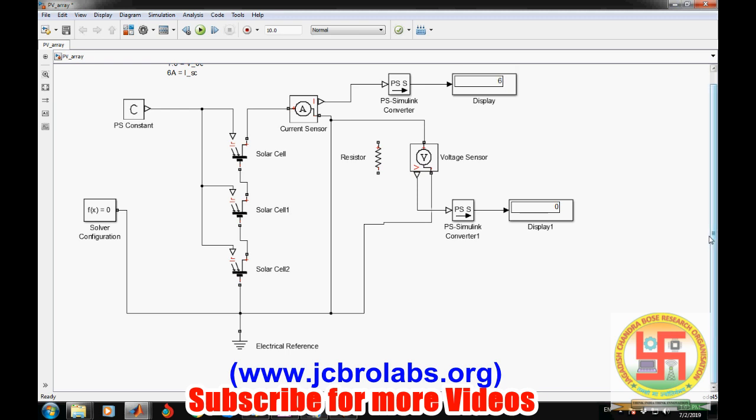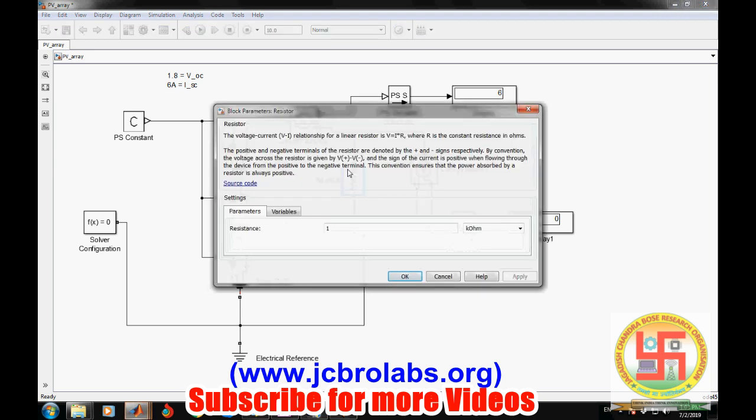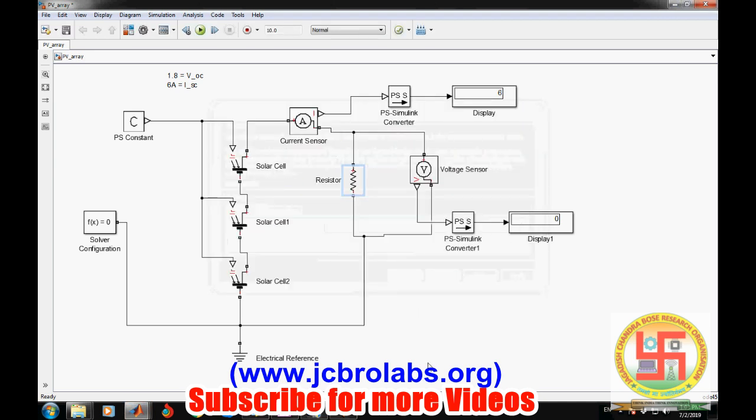So we have created a module with the specifications of VOC of 1.8 volt and short circuit current of 6 ampere, with three different solar cells connected in series. Each solar cell has different specifications. Now let's connect this resistance in series and see the value. Let's say at 1 kilo ohm, how much current or voltage we are getting here.